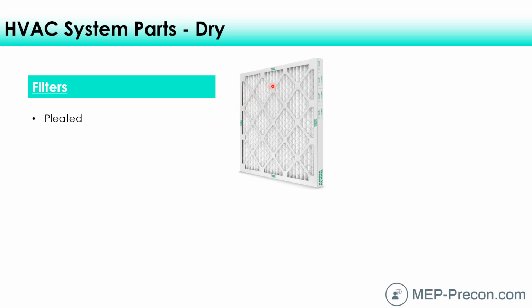And so by having this kind of accordion pleat, it maximizes the surface area such that the air that goes through every little square inch of filter media slows down quite a bit, ideally below 250, around 200 feet per minute or so.